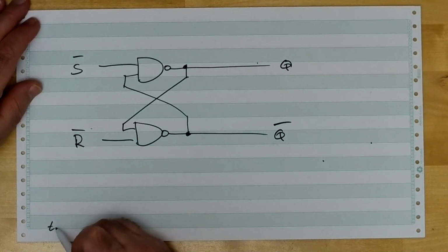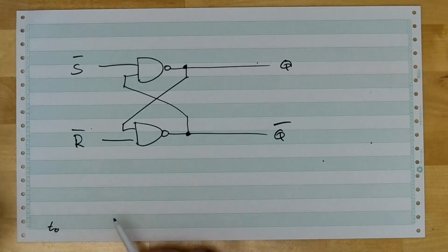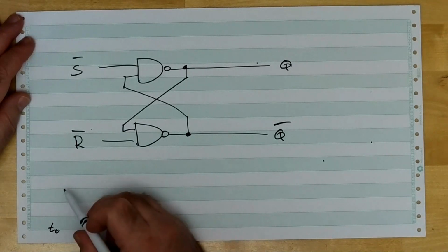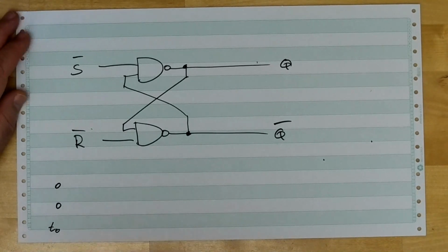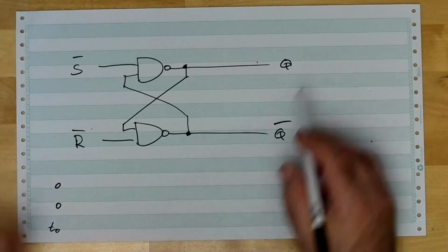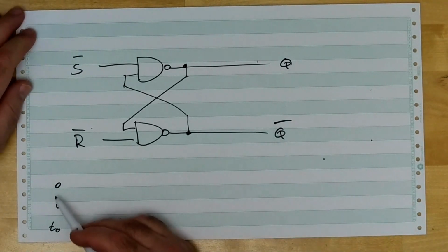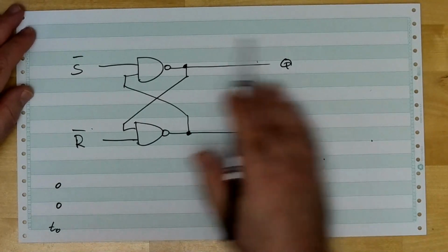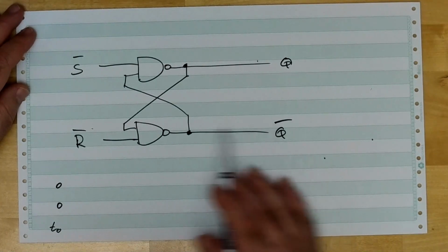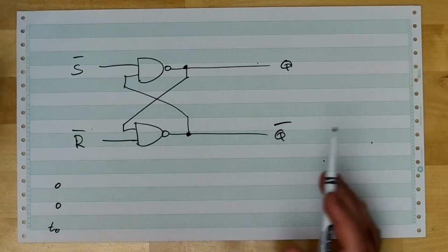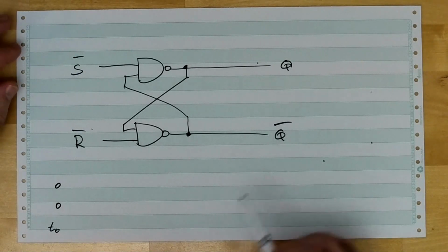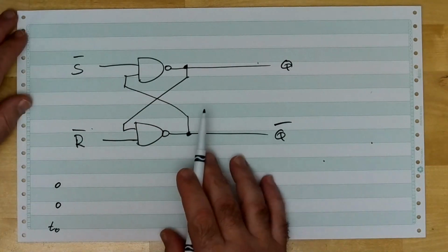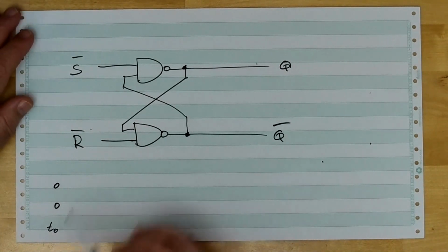So down here, let's keep track. Let's say at time t0, we have what? Let's say this S bar and the R bar inputs to this circuit are both 0. What then is the value of these guys at this time? Well, I chose these carefully because, as you'll see, it turns out we can actually give you an answer. Since these depend on what they used to be, how do we start? You start by carefully backtracking through the schematic. Once you recognize what these are, you pick strategically. So I'm going to do that right now.